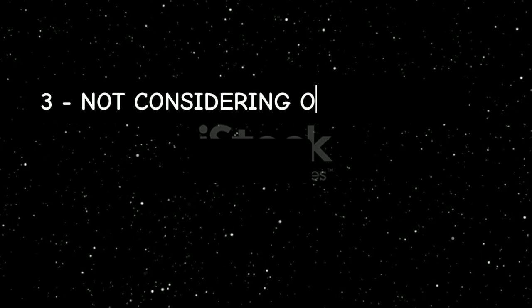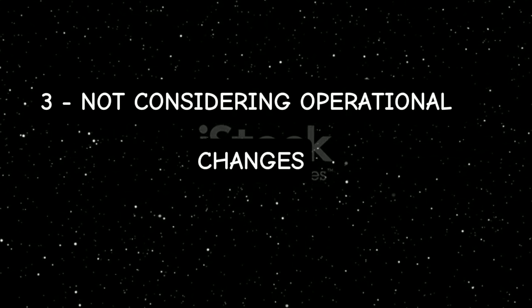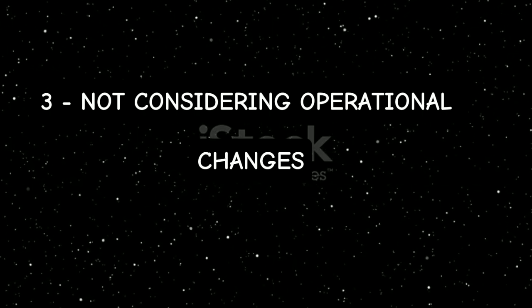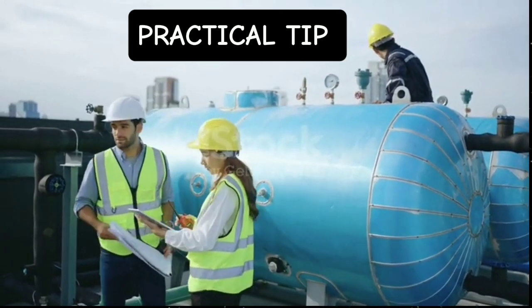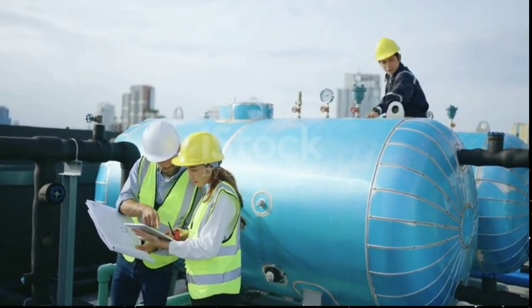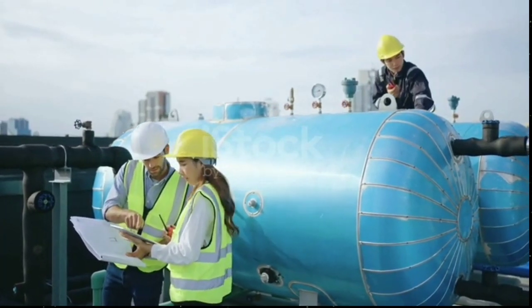Not considering operational changes. Parameters can vary during startup, normal operation and shutdown phases. Make sure you define parameters for all operational scenarios. Here is a great tip to consider. Regularly update the parameters based on actual operation data. This ensures that your HAZOP study reflects real-world conditions, making it more accurate and effective.